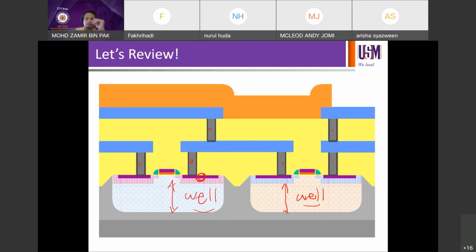While you are writing down, let's say you join an internship or work later at Siltera, Infineon, and the fab. You're going to go through a few weeks of training: process training, safety training, software training. In the process training you'll run the very same thing, like this slide, more or less. They will introduce you from RCA cleaning, wafer cleaning, wafers coming in, the whole process flow, lithography for what, etching for what, implant for what, diffusion, CMP.